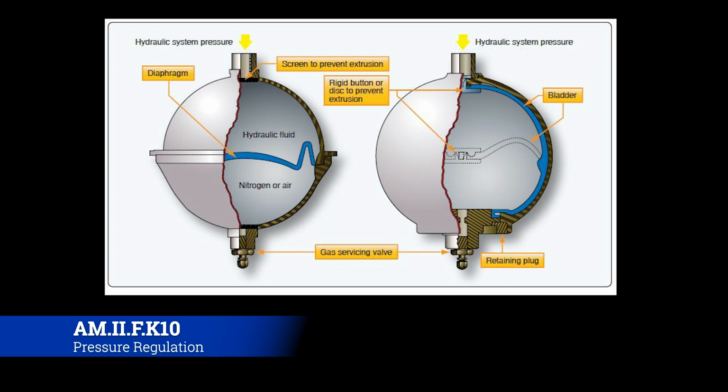What do they do? First off, they dampen pressure surges in the hydraulic system caused by actuation of a unit and the effort of the pump to maintain pressure at a preset level. Then they aid or supplement power pumps when several units are operating at once, supplying extra power from the accumulated or stored power. They store power for the limited operation of the hydraulic unit when the pump is not operating. They supply fluid under pressure to compensate for small internal or external leaks that would cause the system to cycle continuously by action of pressure switches continually kicking in.